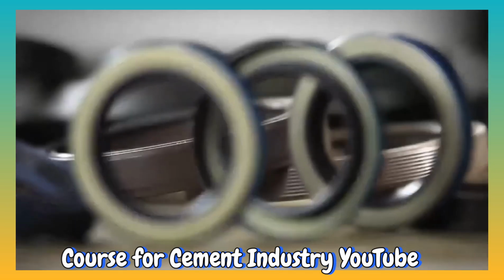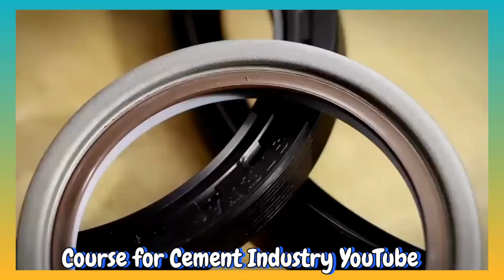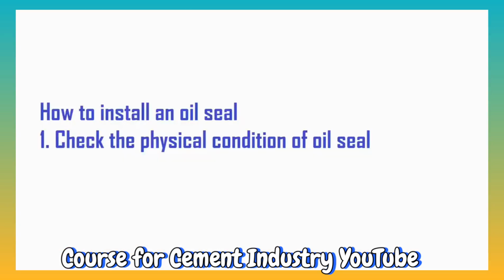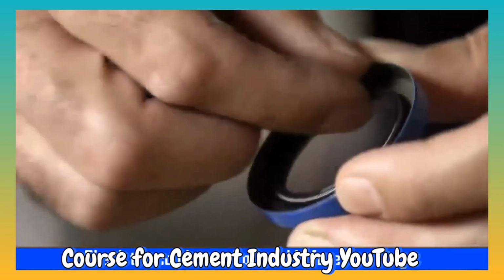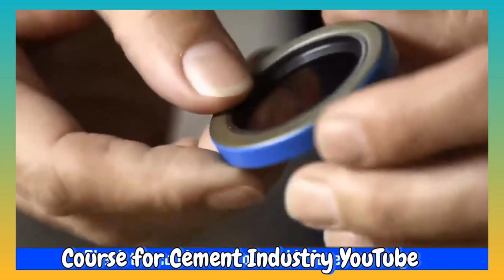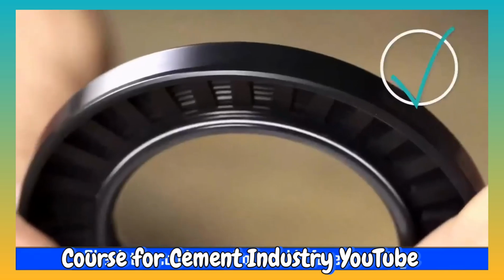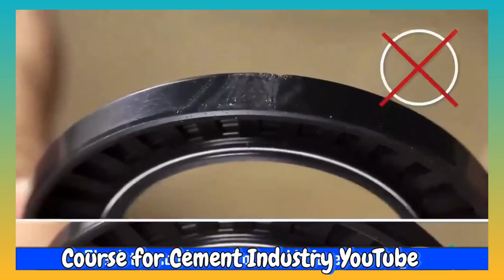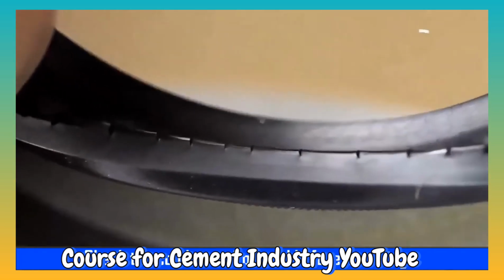After knowing about the function of the oil seal, the following are the steps for installing the oil seal correctly. Check the physical condition of the oil seal to be installed, both from the outside and the inside of the oil seal. Check the condition of the garter spring and the condition of the outer diameter for damage. Check the condition of the edge of the seal lip for damage or cracks. Broken seals cannot be installed.